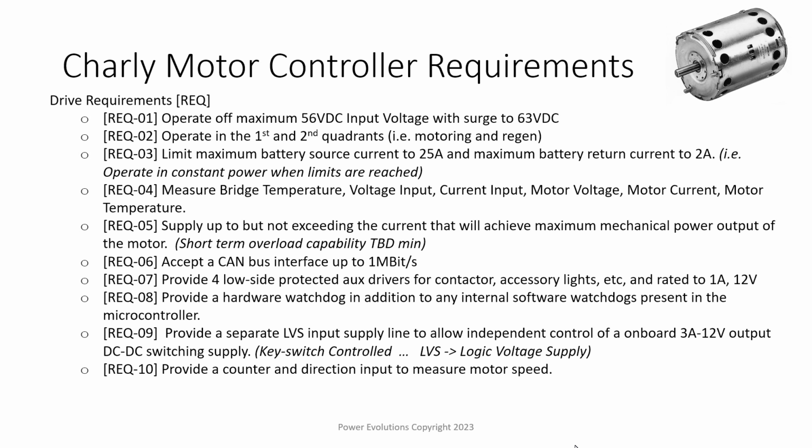I could make this into a really overdone motor controller. It's just cost, right? So when you're rolling your own, it doesn't matter so much how many MOSFETs you put into the bridge. If you're manufacturing this for sale, obviously you want to minimize the amount of MOSFETs you put in, and maximize the output power that you can get out of it.